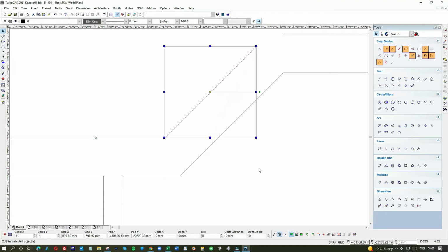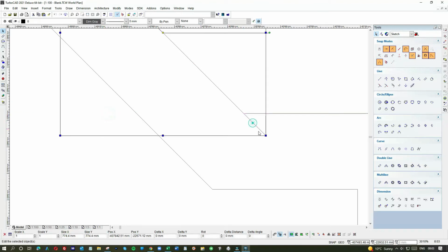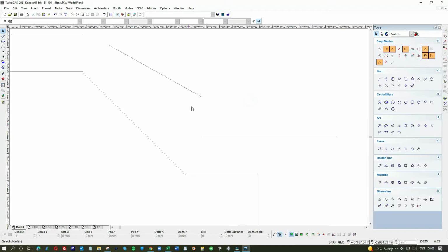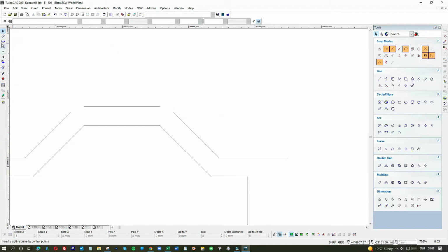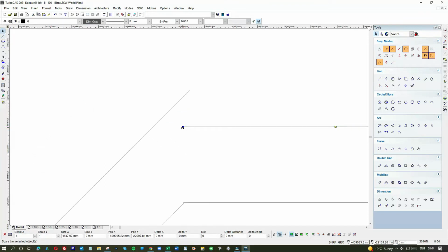I have to use the N here. I'm hoping you actually know what the N does. The N helps you to snap, or if you take that off, take the auto off, it'll snap easier. Right, now you could stretch this line, but you'd be guessing, wouldn't you? So let's just do it this way. And the auto back on.